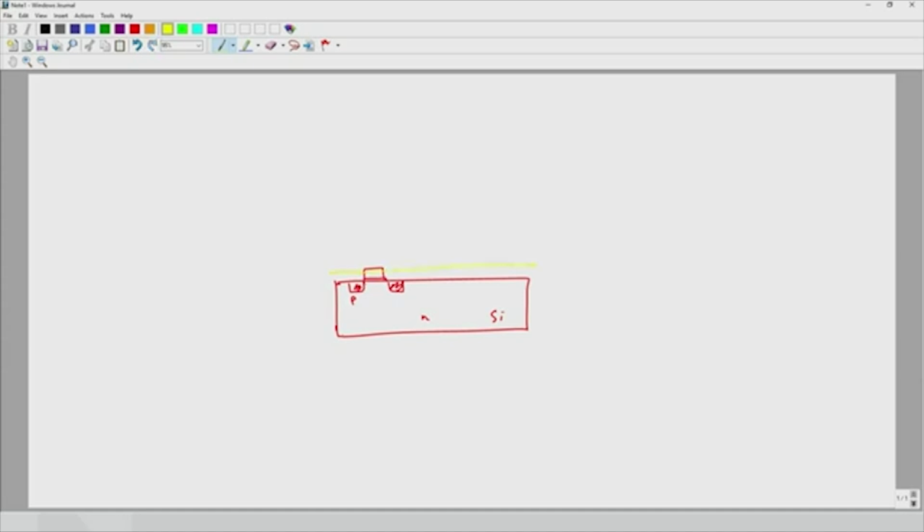Once you coat it with the oxide layer, you want to connect this transistor to another transistor, right? So what we make are metal contacts. You make metal contacts like this, and then further on you take these contacts to connect to either this layer or other layers.